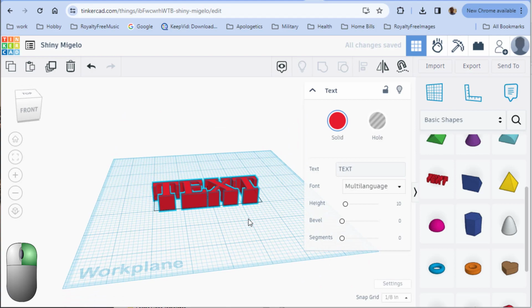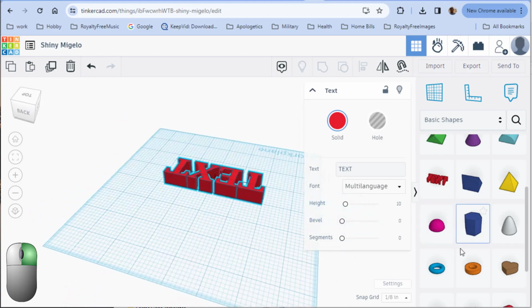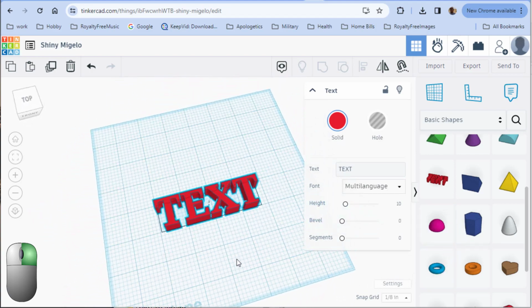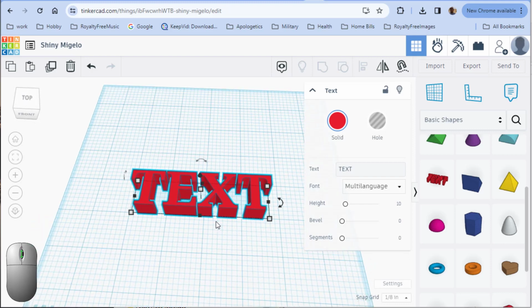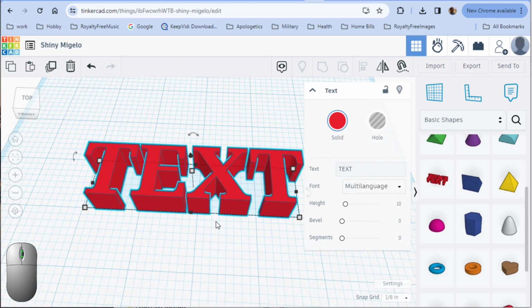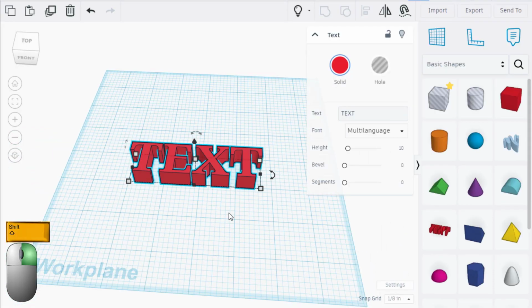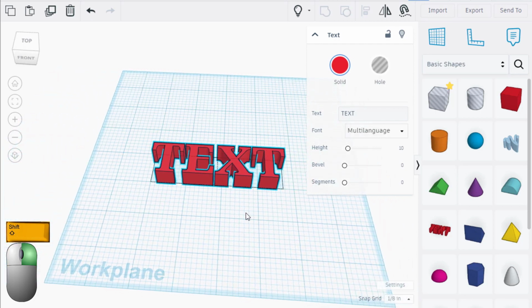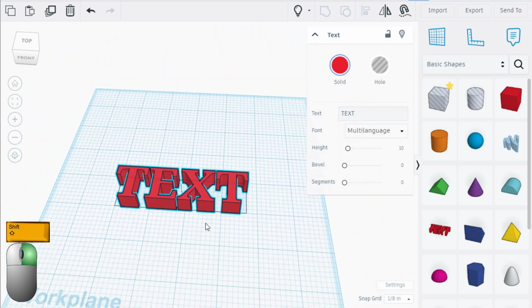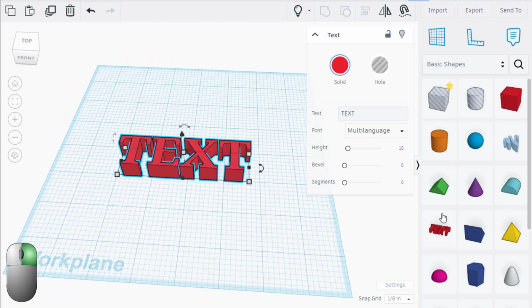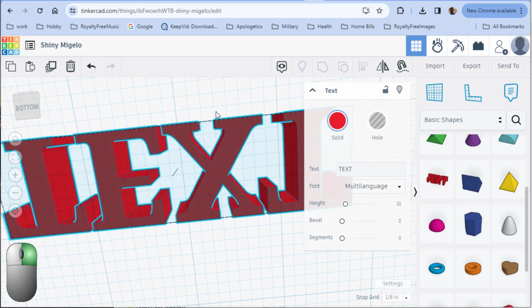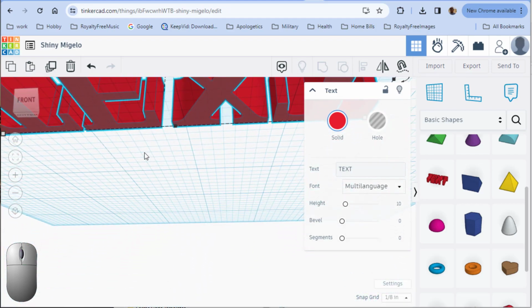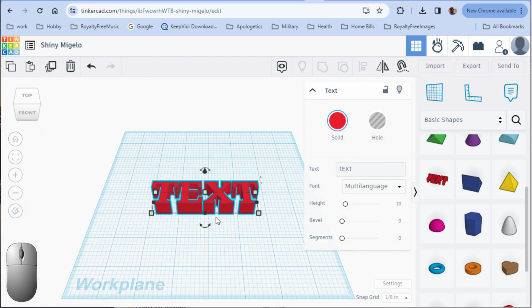By holding the right mouse button and moving the mouse, we can move the Workplane around for more perspective. The mouse scroll allows us to zoom in and out as needed. To move the plane laterally, hold the Shift key and the right mouse button down. Rotating with the right mouse button, notice we can even take a look from underneath the object. If we just want to reset the view to a standard home position, clicking on the Home button will get us there.